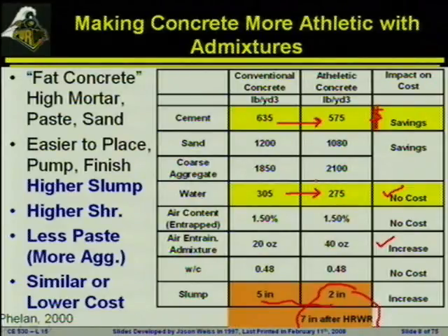These superplasticizers do not react with any of these components, right? So how do they exist in the hardened system? Well, the question has to do with if they react with anything that's in there and how they exist in the system, in the hardened. Some of them will be absorbed into the hydrated products. Some of them will stay in the pore solution. Some of them will just stay on the surface of the cement particles.